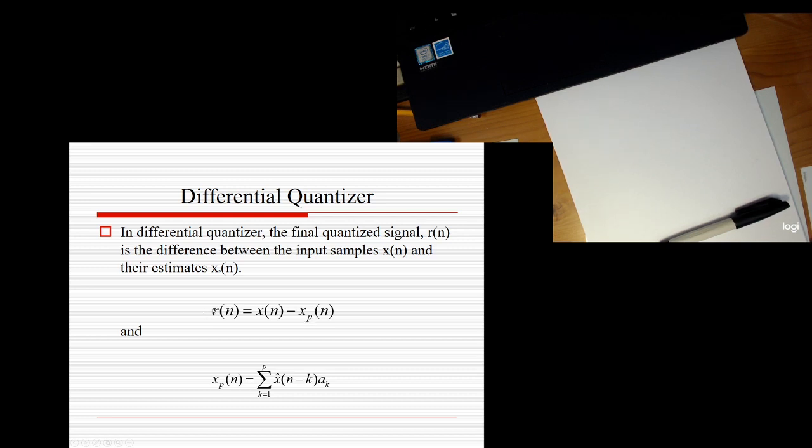So we can get a residue. This is more like a deviation, so a deviation signal. So here, maybe residue. Here the prediction is based on previous data. So you can see it is based on S hat n-1, S hat n-2, multiplied by coefficients. This one is based on the decoder. So you can see it's not based on previous S of n. It's not based on the previous signal. It's based on the decoded signal.